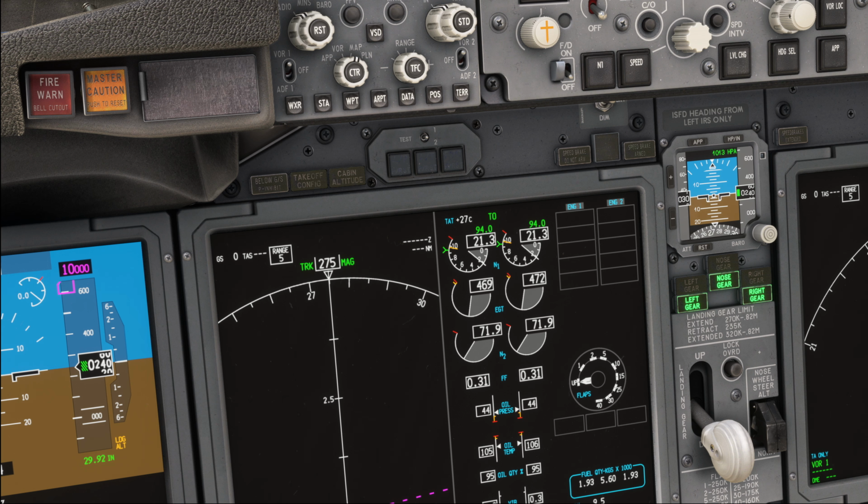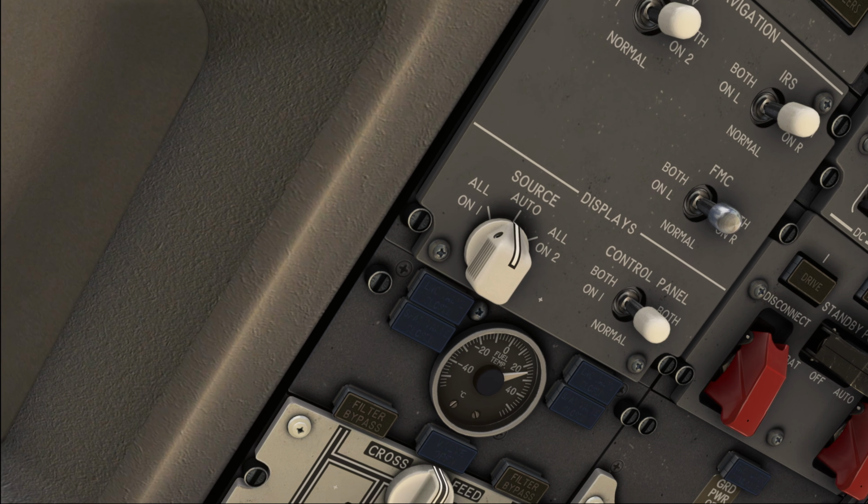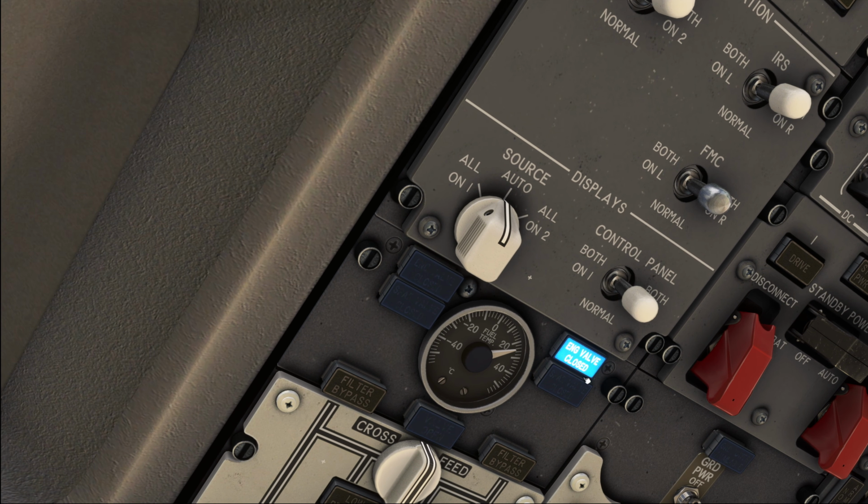During this test, the fuel flow will indicate 0 and the engine fuel valve will open and close repeatedly, which can be seen by the indications up here on these valves. So you will see them flickering when the engine is started up. The engine valve close light will illuminate and remain bright blue during this logic test and will extinguish when the test is complete. Once the test is complete, the engine start sequence continues.